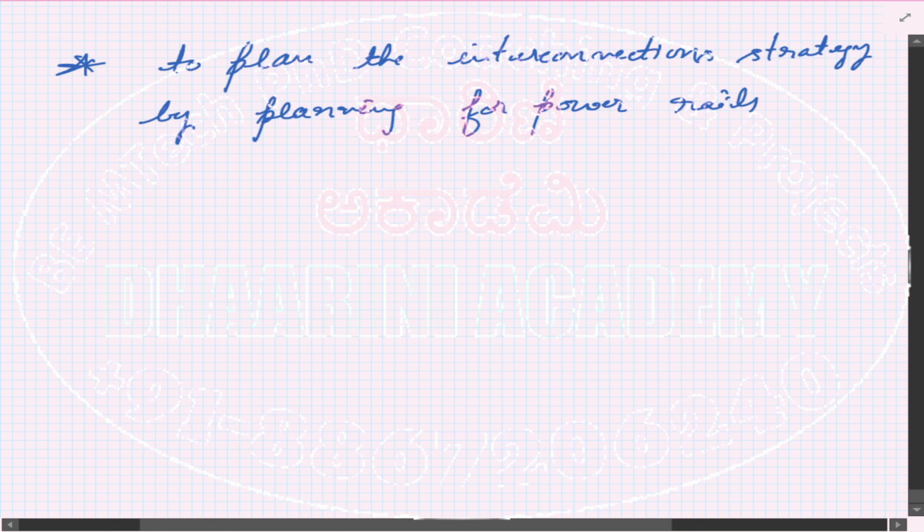It indicates where the lines of power supply will go through your circuit, which parts of the circuit will get direct access to the power supply. This is very important because the circuit components which require higher power or have high power dissipation, you want to keep them close to the power supply.